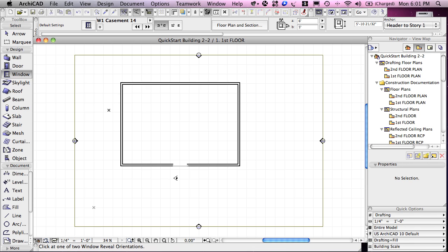Now here is the eyeball cursor allowing me to say this is the outside direction. Now if I go to the right side here, again there's a tick mark that indicates the center point of the wall. Now that's very useful, and in fact probably is the most common one to use, but you will need to switch it from time to time.